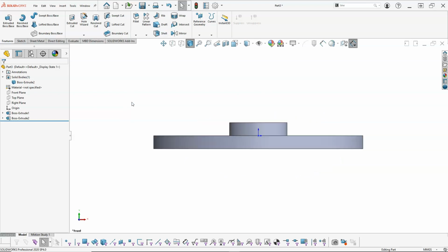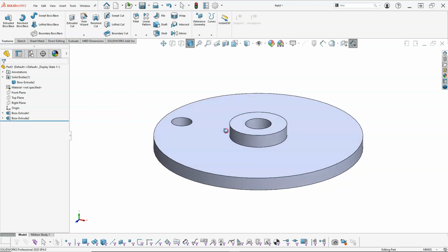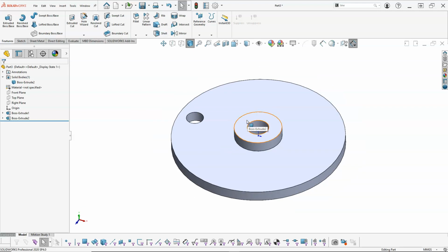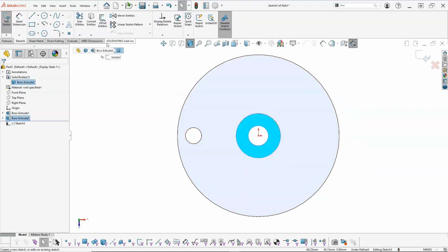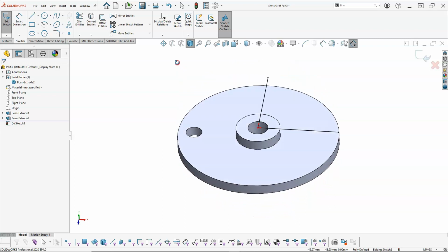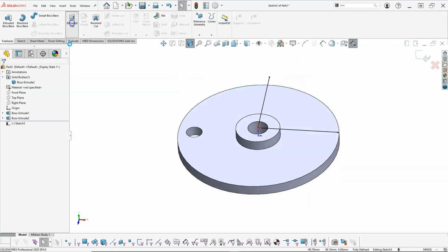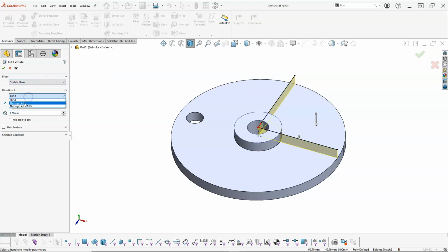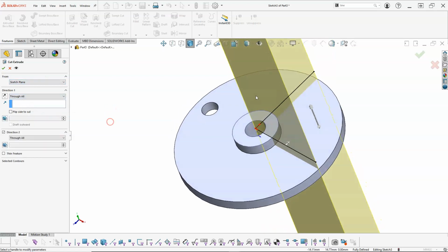All right, so the contrast with a revolve comes into play if I were to split these. I'm going to open up a sketch, and it rotates over, and I'm just going to quarter this. So basically cut it in half again. And so if I draw a quarter and then cut extrude, we're just going to tell it to go through all. Now with a through all and an open profile, it needs to know what we're cutting. So right now it's going to take out this section of the pie. I want to flip the side to cut, so I only end up with that quarter section.